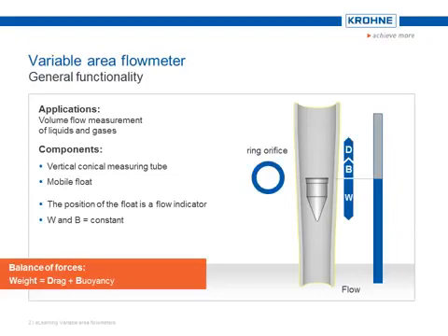The gravitational force and the buoyancy force are constant for a specified application. Only the flow force can vary temporarily, as a result of a change in flow which moves the float into a different position.